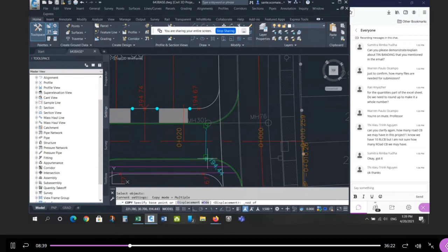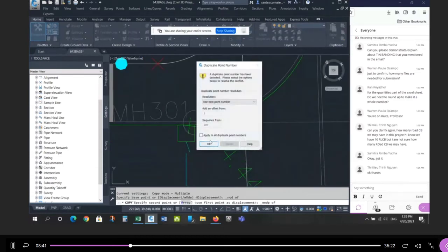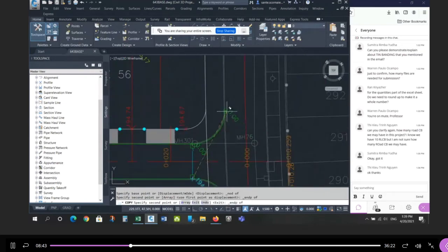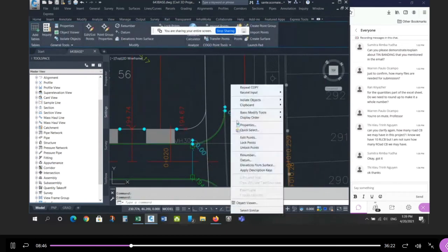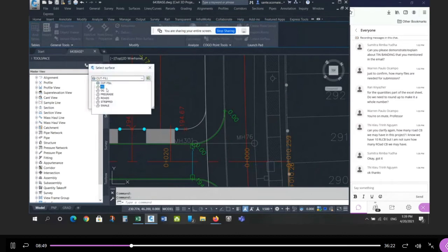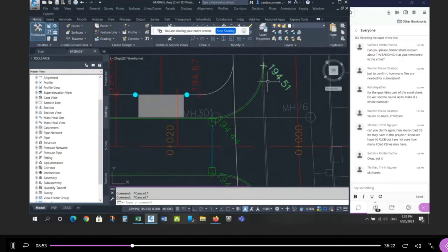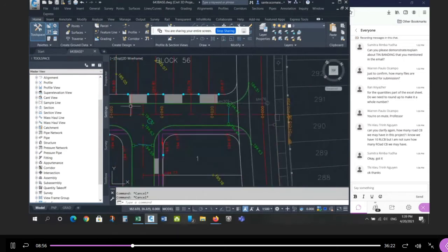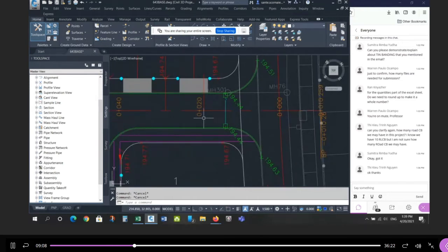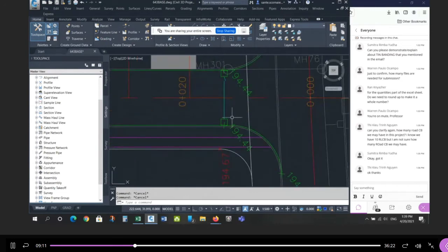So if I make a copy of this point from the node to the end point to this end point here, and I get the elevation from the roads. So I had it backwards, I think. Yeah. So you can see actually this comes from here, it comes down this way. And then from here, we know it's falling this way. So water is coming from here toward both of these catch basins. And from this road, water is also falling this way and this way. So because we're receiving water, again, from both sides, then we may consider putting in double catch basins here and here, okay, based on the standard.